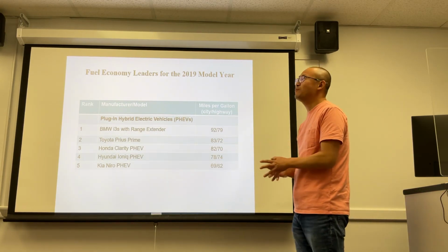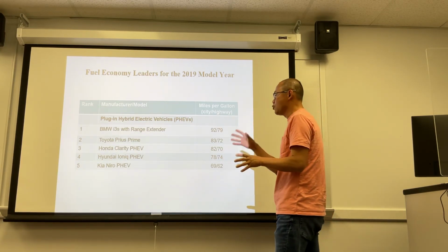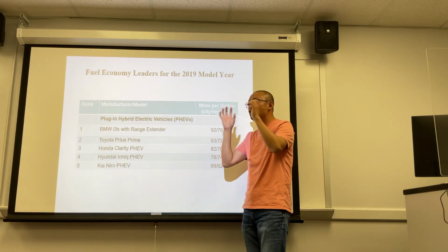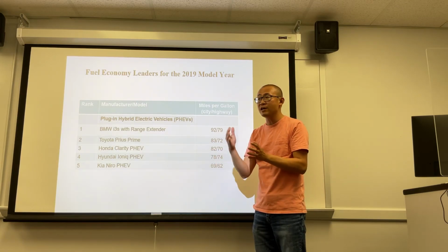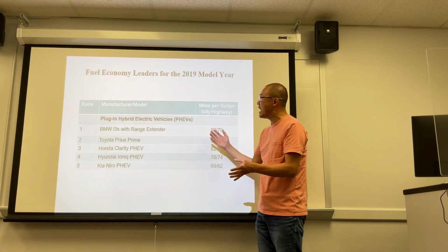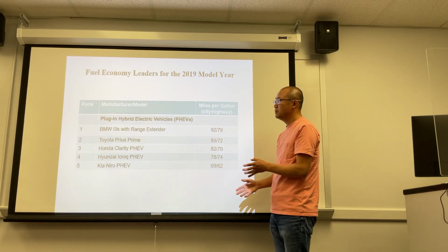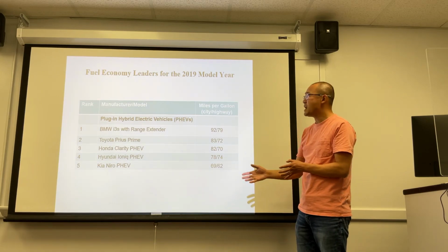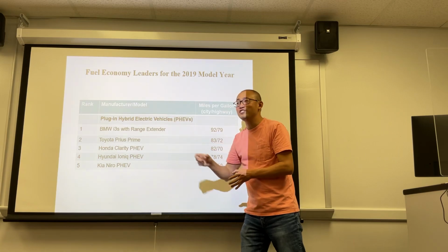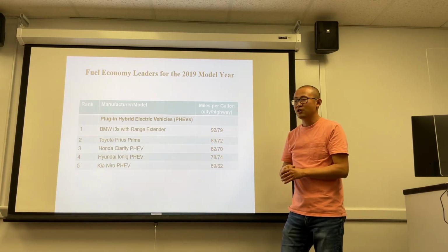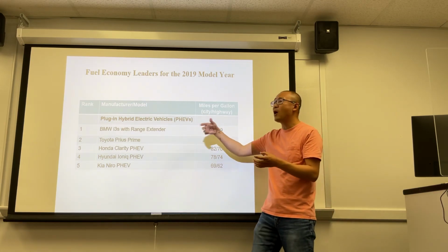There's another type of hybrid vehicle. Like we said, Toyota Prius, you're using friction to power the battery, to charge the battery, so that it can be used at low speed. But there's another type of hybrid vehicle called a plug-in hybrid electric vehicle, PHEV. Plug-in means what? You can charge it. So the battery in the plug-in hybrid is chargeable through a power outlet.